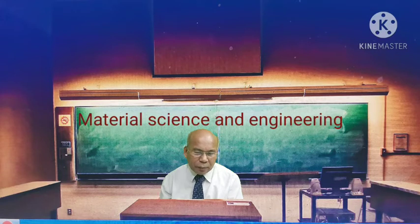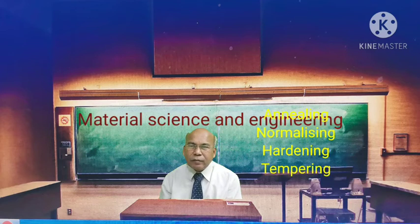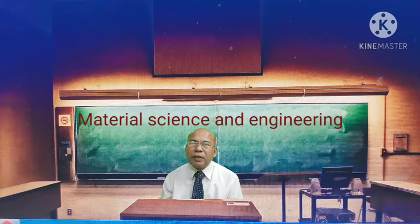So the important heat treatment processes are annealing, normalizing, hardening, pack carburizing, and so on. In the case of the annealing process, the main purpose is to soften the metal.